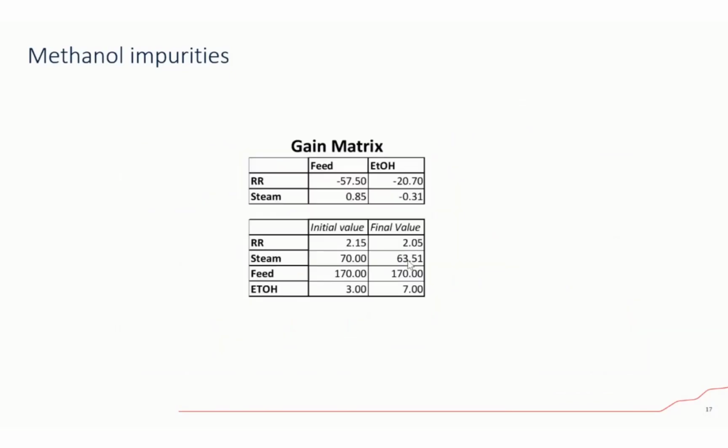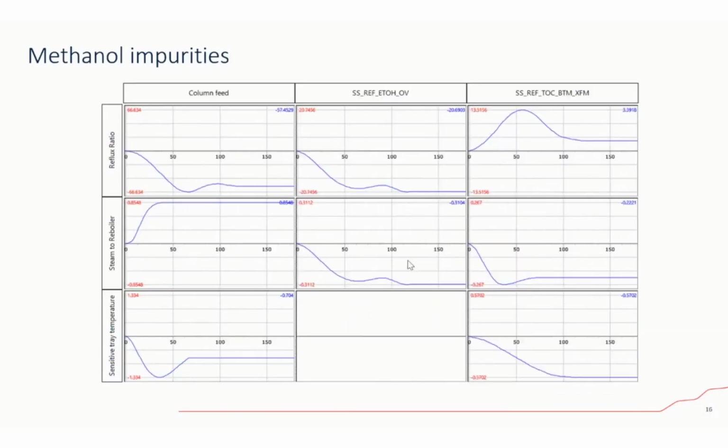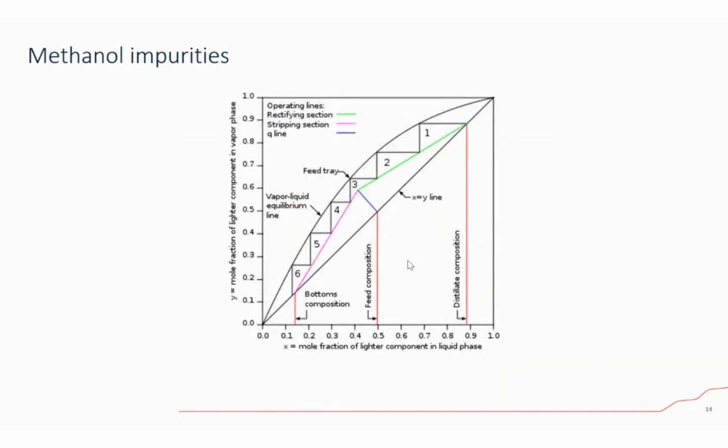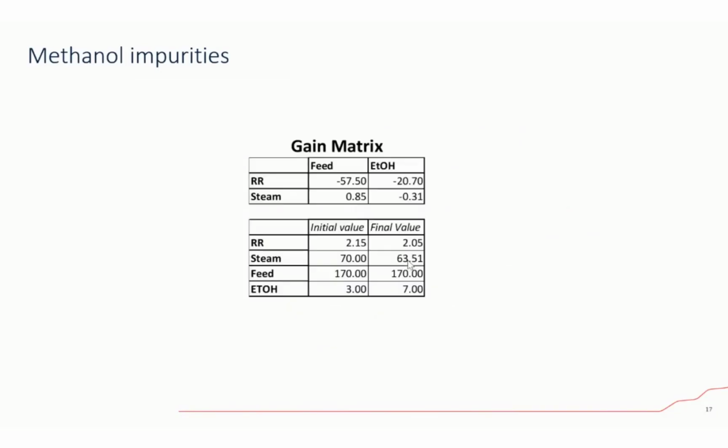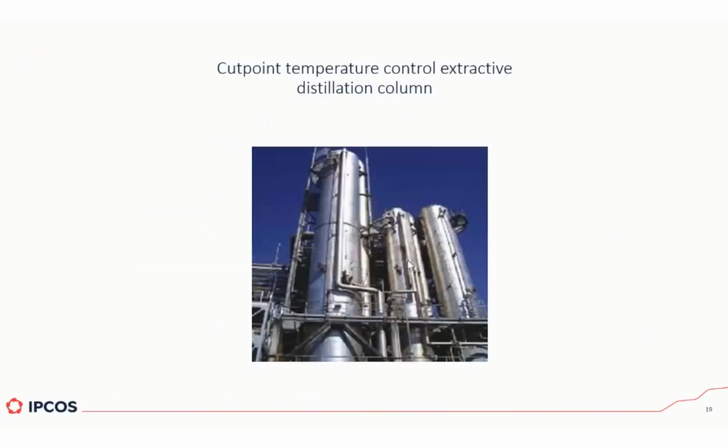it's not as simple as it seems, because you have all these interactions. But bottom line, what allowed us to do this was the fact that we got to know the process enough. And that's why we managed to do it. We had the chemical engineering knowledge, for example, to know that to build a soft sensor there, we had to use something different than just temperatures, because they were never going to work. And yeah, that was the final result.